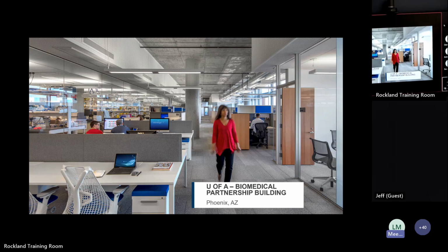We've done a number of installations at the University of Arizona, and on this particular project, it's probably a little hard to see, but over on the right side near the perimeter area, we have the exposed open ceiling 24-inch wide linears, but there's a wing on the side of it as well. If you have an open ceiling, there are options across manufacturers to have wing extensions to maintain that Coanda effect. So even with an open ceiling without a ceiling grid or ceiling tile next to it, we can still maintain proper air distribution.